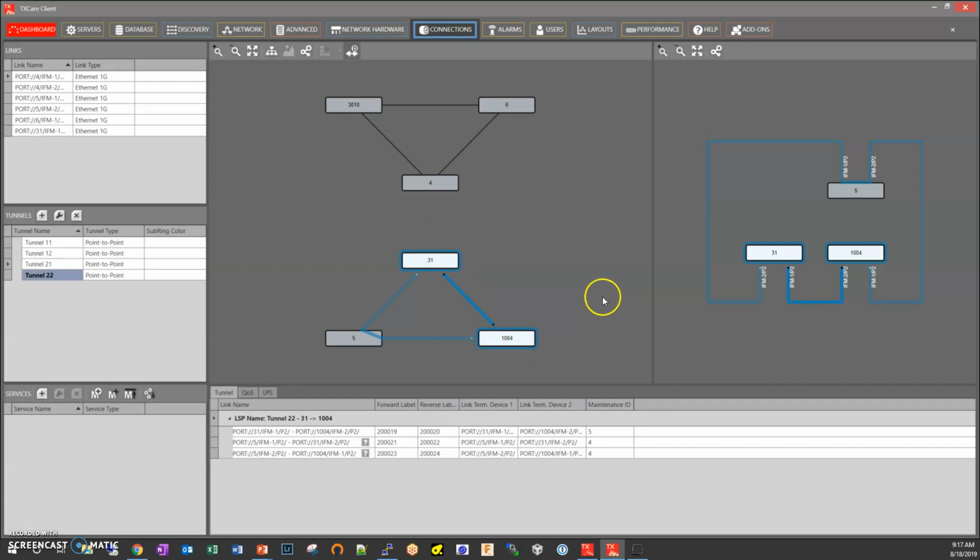So effectively by doing this, I'm connecting a C37 application here, which is going to be a transfer trip Schweitzer DTT application across here and back down to node number 5, and the second application going over the Schweitzer mirrored bit serial converters between node number 6 and 1004, and between these two serial converters I'm going to run a mirrored bit tester to see and monitor latency and so on.